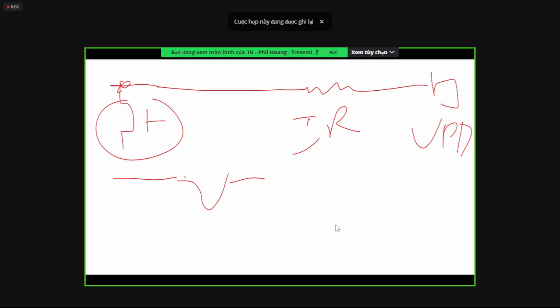So by having this macro far away from VDD, your droop is bigger, and in some cases it can exceed your limit. So what you want to do is put the macros closer to your source. That means the current is always the same, but the R is reduced, so your droop is no longer big, right?